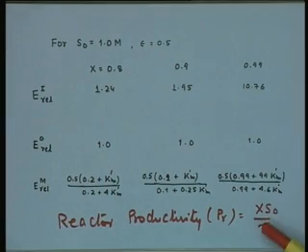Now, I was just trying to relate productivity and the quantity of enzyme or the space time. The quantity of enzyme required and the space time are almost analogous parameters. Their behavior on the basis of the fractional conversion required is identical, but the effect of the fractional conversion on reactor productivity is just the reverse, because tau appears in the denominator, x S0 upon tau.